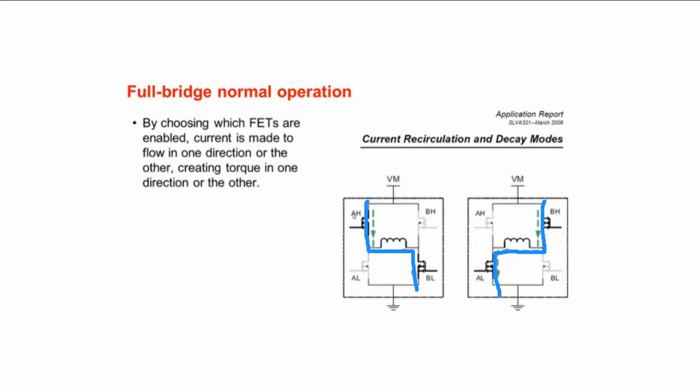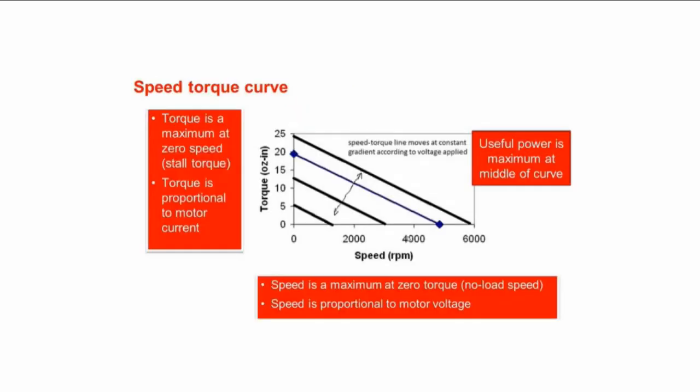And notice, we will never want to turn on both the high and the low switches in the same phase, which would create a direct path from battery to ground and a very high current path. So this comes in part of the intelligence we have to build into the motor drives: as we switch from the high side to the low side being on, there is what's typically called a dead time, a period where both have to be turned off so that we don't get what's called shoot through current.